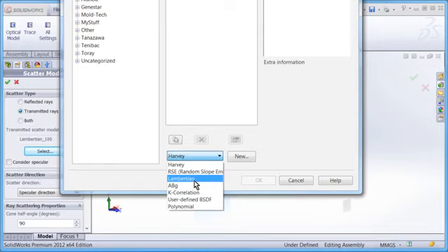As of the 2012 release, we've added several more extensions and enhancements to the scatter modeling that will allow you to simulate texture or scatter profiles using ABG information, K-correlation data, your own mathematically defined BSDF function, as well as an M by N polynomial model. And all of these are explained in all of the online documentation that comes with Apex.